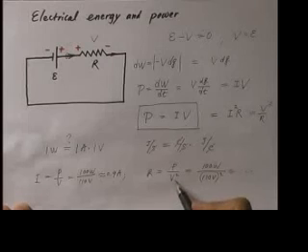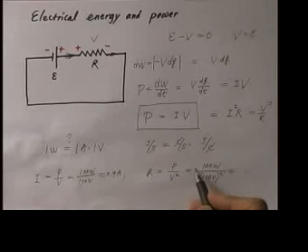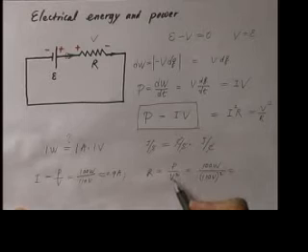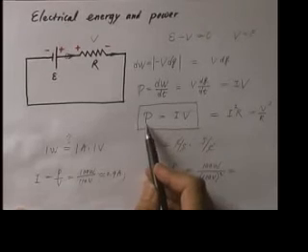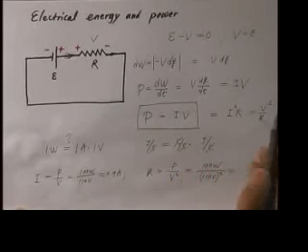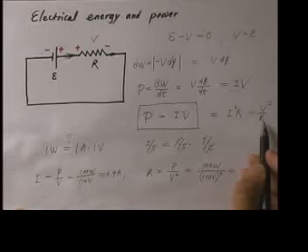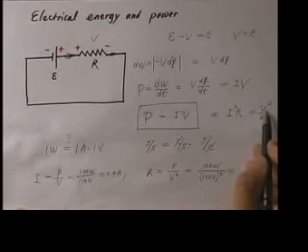Of course, if you put the same light bulb on a different power supply, which says, instead of 110 volts, it says 60 volts or whatever, then you're not going to produce the same amount of power. R is the same, presumably, assuming the temperature doesn't change by much, but V is not the same. V is smaller, and therefore the power will be smaller.